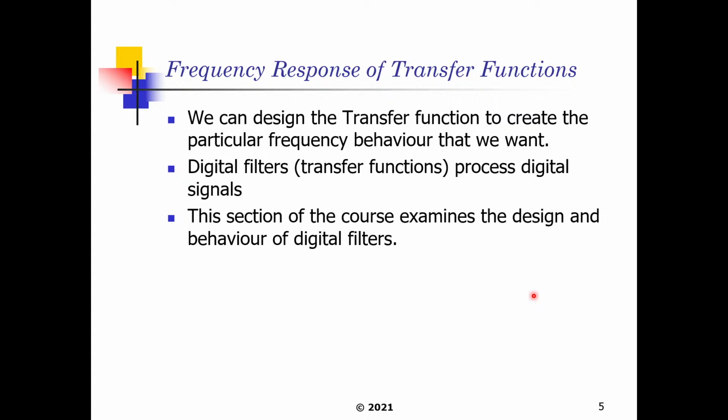So typically, when you're doing some sort of filter design, you need to design the transfer function to match the frequency response or the frequency behavior of your system that you require. We saw this in continuous time systems, where we had the Laplace transform being the design tool required for us to develop analog filters. But we also saw that the Laplace transform doesn't work well for sampled or discretized signals. That's why we have the Z transform. As such, the design process for the Z transform when you're making digital filters is going to be a little bit different.